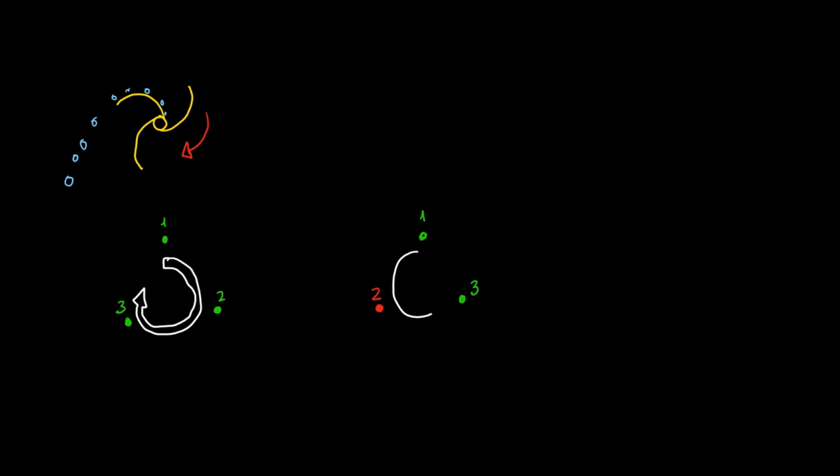Sometimes you run into a 3-wire pump, frequently brand new, and either it doesn't pump or there's very little pressure. Before you run to blame yourself or someone else for their poor sizing, or you rush to buy a new pump, take 10 minutes to check that 2 cables have not been swapped around. If the order 123 is changed to 132, the pump rotates in the other direction, and while it is still able to pump, it loses a lot of power. It is very easy to have a misconnected pump and think it is defective.